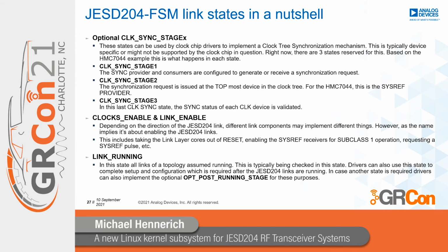Clocks enable, link enable. Depending on the direction of the JESD link, different link components may implement different things. However, as the name implies, it's about enabling the JESD link. This includes taking the link layer cores out of reset, enabling the sysref receivers for subclass 1 operation, requesting sysref pulses, etc.